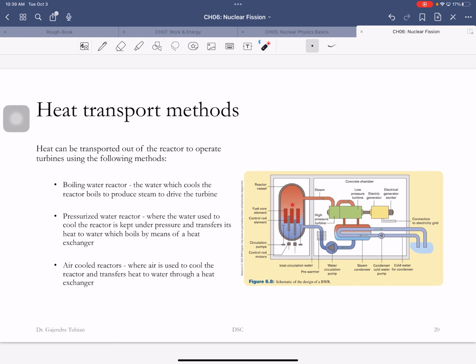So you're producing heat, you pump water through it, which acts as a moderator and a coolant. This water turns into steam. The steam is turning blades in a turbine, and the shaft is turned, and that shaft is turning the wire in the electric generator. The wire is sitting between magnets, and that's converting mechanical energy to electrical energy. Okay, so that's the reactor.